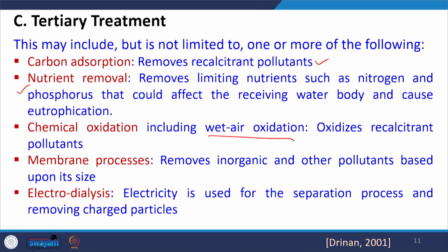Overall, RO methods have the disadvantage that some amount of water has to be rejected, and it has to be further treated via evaporation or otherwise, so as to handle the total amount of water which is generated, and this RO is mostly used in those places where ZLD is to be done. So, when zero liquid discharge is implemented, RO is used.